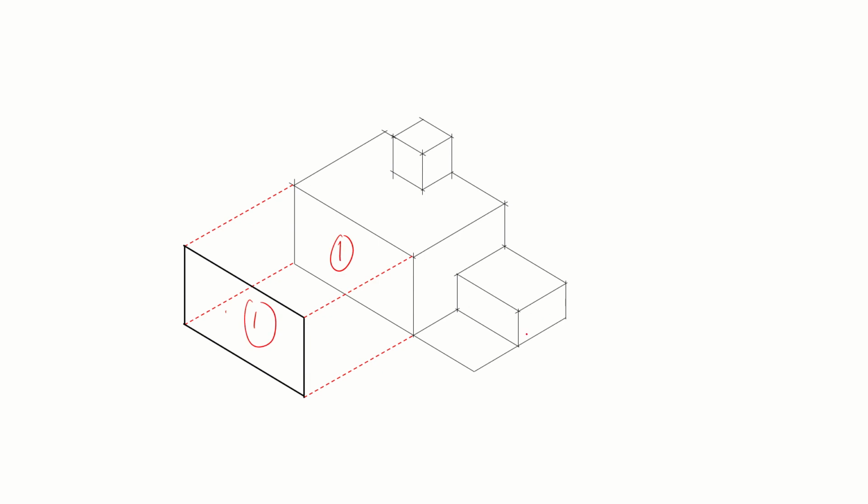Now we have more sides here. We can see how it can be done. You can see on top we have this headroom. I'm now projecting this point here because that's how it will look. Project this point, or put the height equal to the height of this. Put this height equal to the height of this. Now project this point, and connect it. So that is also connected here.